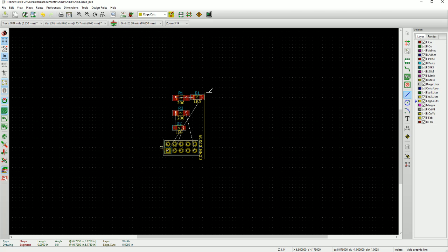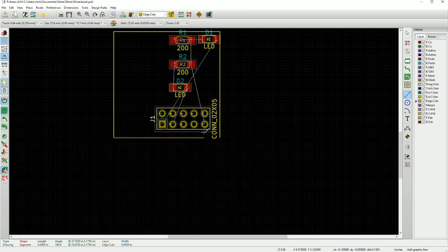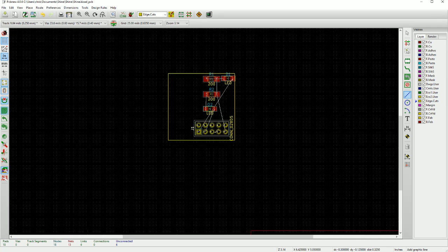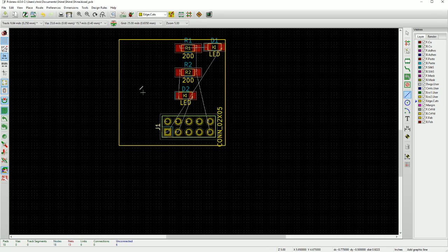There we go. So I'm at minus 100, 1.000. I'm going to go over by 1. Now I'm looking at DX, minus 0.1000. This should go back down to 0 now. There we go. And then I can zoom in and I'll finish this off. Okay, so now that is a 1 square inch board that we're going to use as our outline, right?